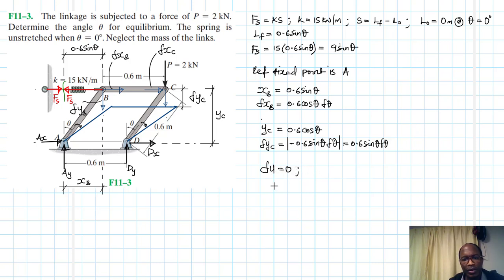Therefore, let's start with the points where we have active forces. At A, we don't have any translation of forces in the X or in the Y, so no work. We don't have any couple moment there, but we have a rotation of virtual displacement, so no work. At B, we only have work in the horizontal direction, no work in the vertical at B.